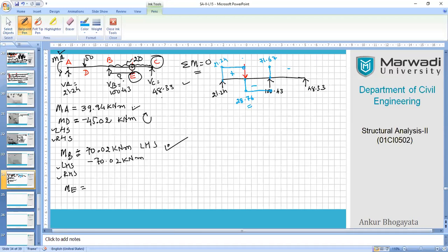So go for the UDL, and 71.67 minus 120, isn't it? Because 20 is the load and 6 meter is the span, so 6 into 20, as simple as that, minus 71.67. When you do, you reach this answer, that is 48.33, but your answer will be negative, so you have to come down here somewhere. I will subtend this and try to join these two lines together.